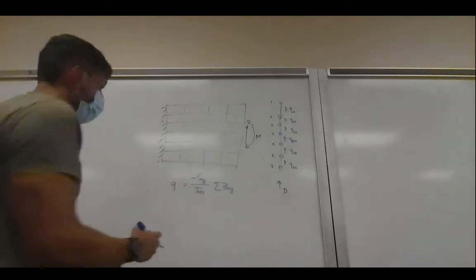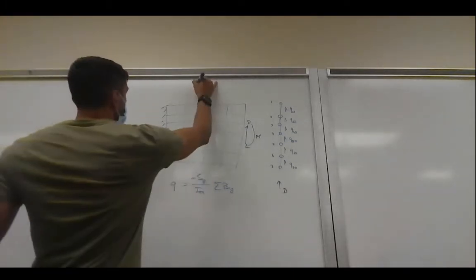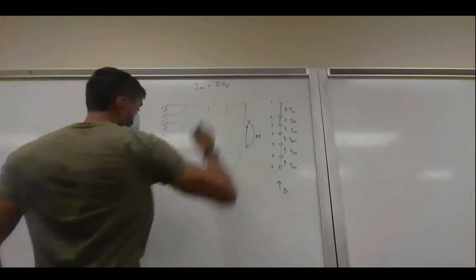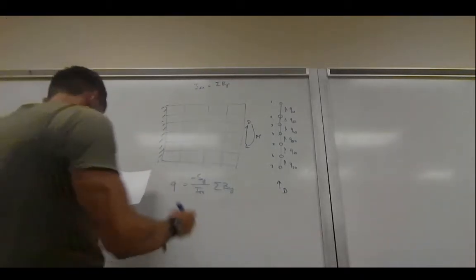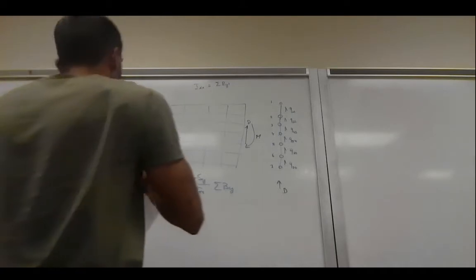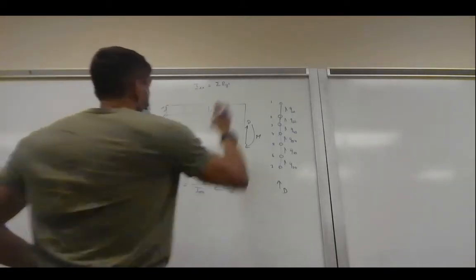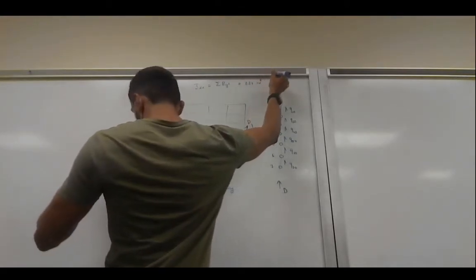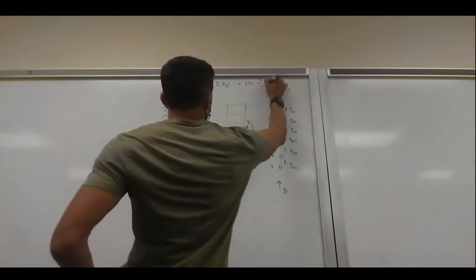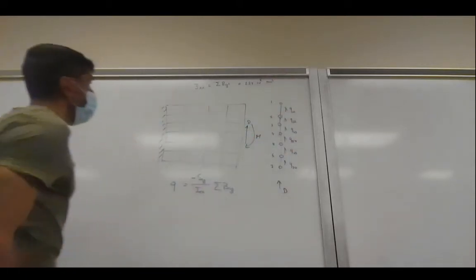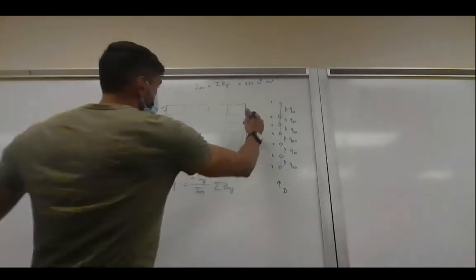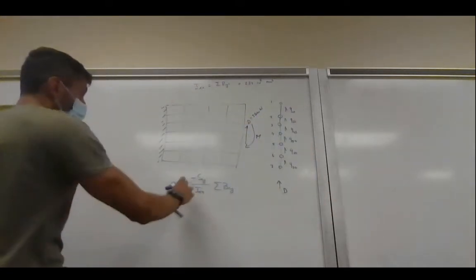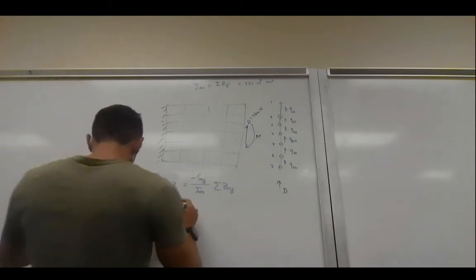So the shear force is given. The moment of inertia, of course, that's your standard moment of inertia of boom. So that's nothing else than the summation of By squared. And if you did that correctly, you get a number out of it, 2.24 times 10 to the power of 8 millimeters to the power of 4. So we know this, and then of course we can substitute the 5600, so this was 5600 newtons. We can basically get a number out of here.